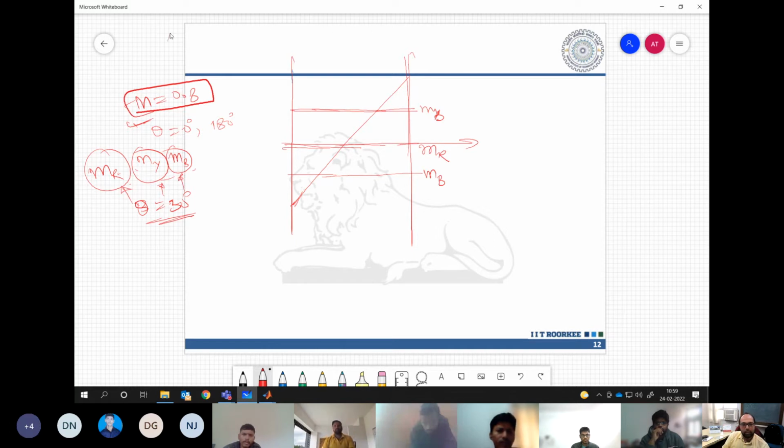Or I may say that the motor is running at 40 Hertz, 50 Hertz rated motor is running at 40 Hertz, which means what? V by F has to be maintained. So that means my modulation index is basically 80% of the full value. You understand this point?